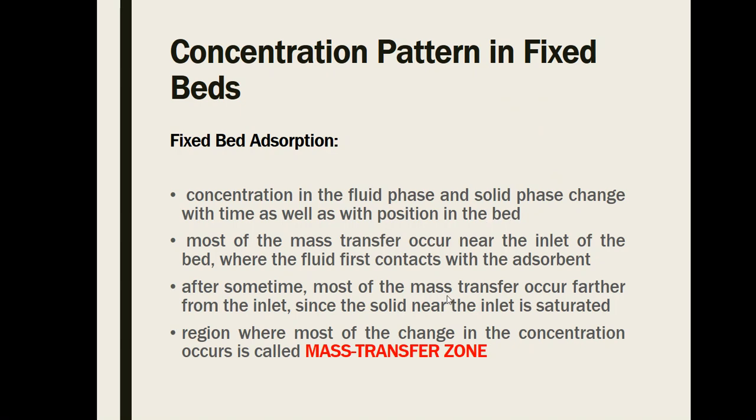Meaning once the solid in the inlet part of your bed is already saturated, it would be the next part which will follow the same pattern of adsorption of the component from the fluid. After some time, most of the mass transfer occurs farther from the inlet, since the solid near the inlet is already saturated.